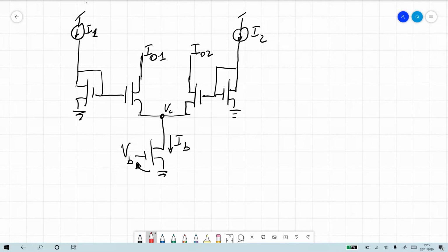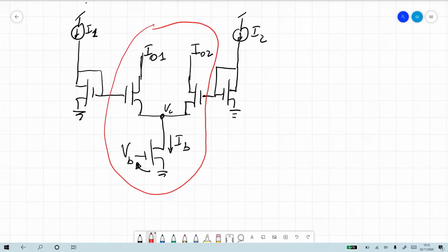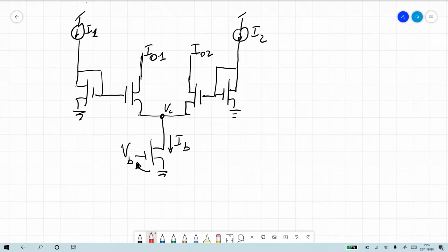What you should realize is that what you see here is the differential pair. We've studied that and analyzed it to the end, so you would imagine, what can you do more with the differential pair? Well, just by connecting it to currents and copying the currents in, you get a new building block that is actually extremely useful. But let's go through the circuits. Let's assume all the transistors are in subthreshold, in saturation. Let's just look at what happens at the input currents and the output currents.